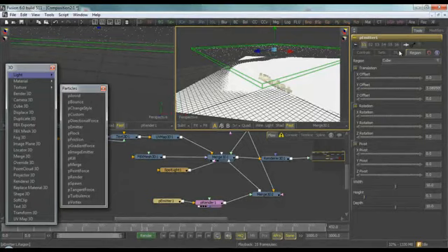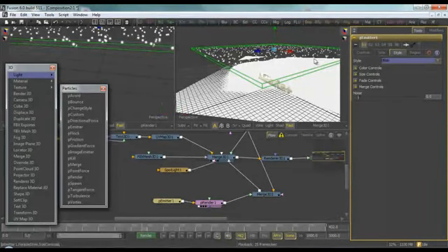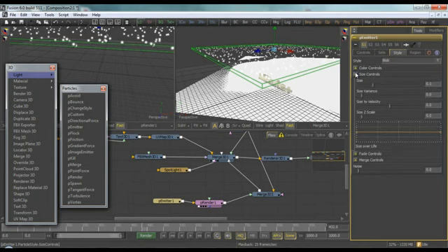So let's set up the style of particles. By default it's on point, but we'll go to blob. We'll leave the color on white. We'll go to size control and play with those settings a bit. We have to make it really small, 0.075.